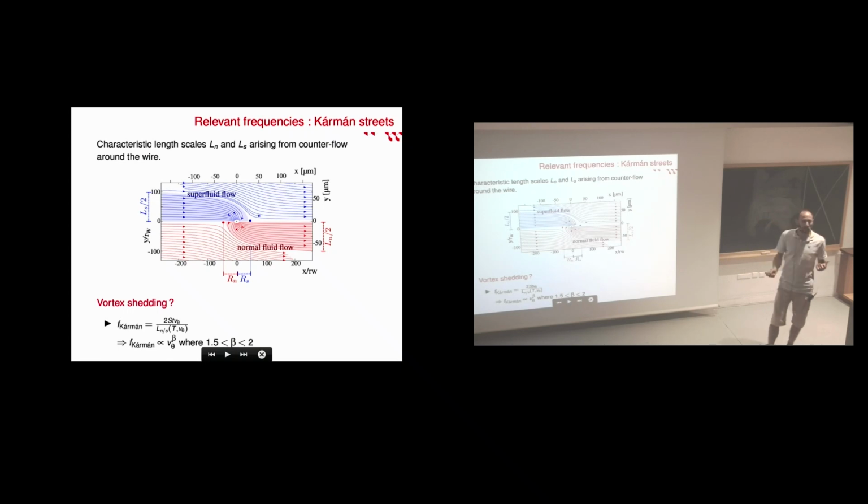This would lead to the right exponent, but it has defects. The problem is that this is very temperature dependent, which it should not be, according to what we have seen. We are looking for something that doesn't depend on the temperature. And furthermore, we would not expect that the turbulence acts on this vortex shedding as it does. It should simply enlarge the bump rather than changing the frequency of the bump. So this candidate has been eliminated.